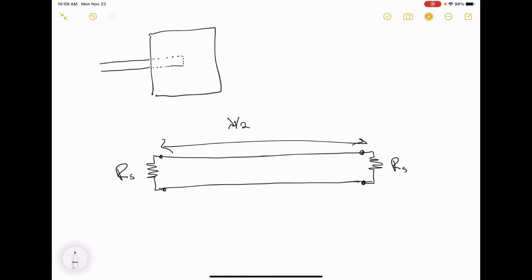And transmission line resonators have some interesting properties, including that no matter what location you choose to put your feed point at, the input impedance looking to the left and the input impedance looking to the right have a specific relationship when at resonance.